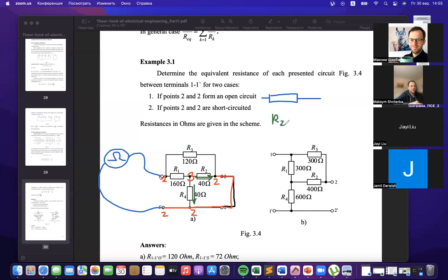In this situation, first of all, we could replace the resistors in parallel, 40 and 40, and obtain 20 ohms. You may ask how we should know which resistors we should start from, and if we want to start from the first one or from the third one, what should we do? Not every resistor can be replaced in the order that you want. Sometimes you should find the appropriate order and start not from just any resistor, but from a concrete one.